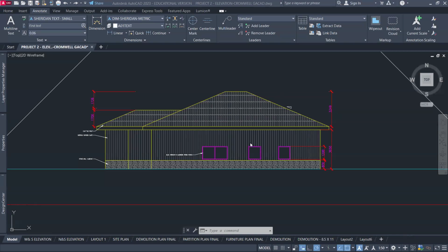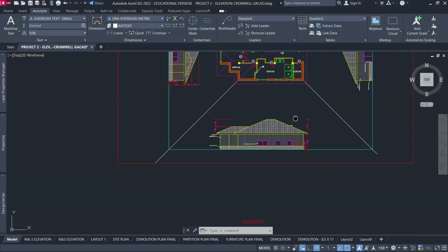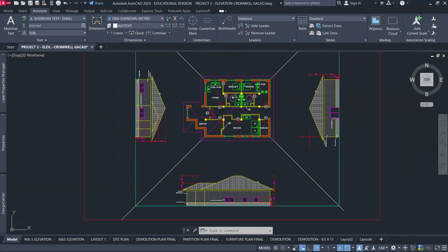Now that we have the south elevation, we would like to connect and do the east elevation. Okay, so again, 45-degree angles so that we know how far each one is from the building, so they're the same. You connect the ground line to the 45-degree angle, and then you can create a vertical line. That's how far your elevation can be. It's not mandatory. You can always go further away, but this one gives you some type of consistency.